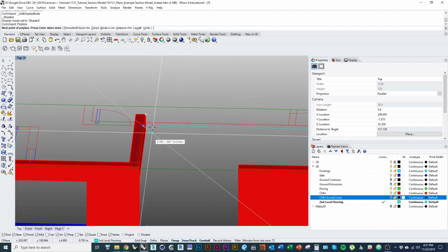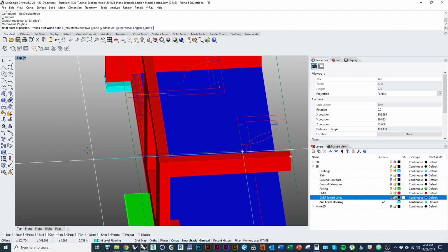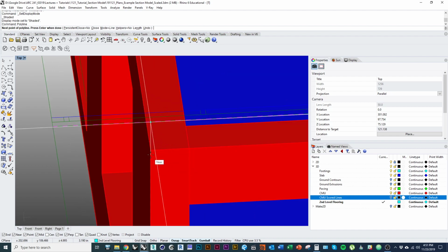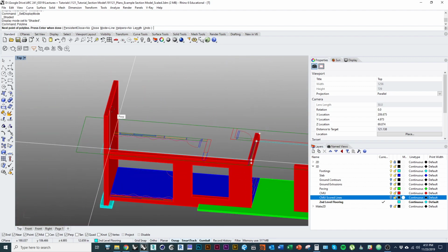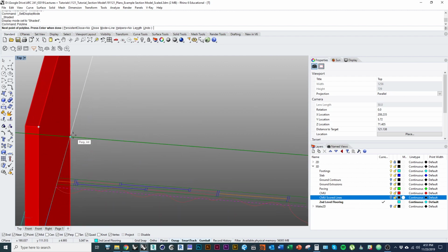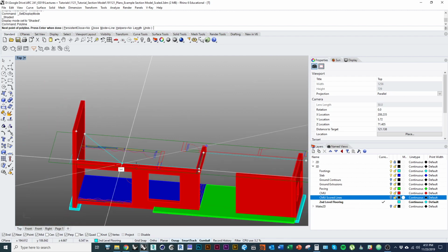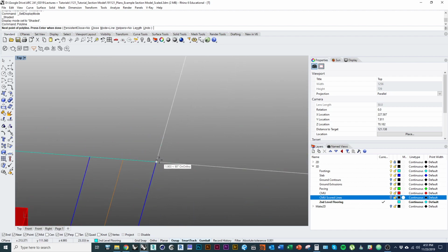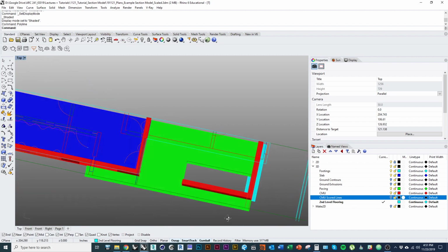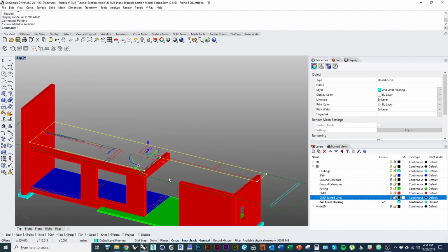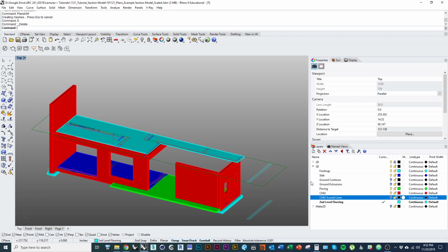And then I'm also going to use my walls below to define where certain edges should go. Oops. So I'm just holding Shift and hitting Tab to constrain my next point to that direction. And then I'm using those walls below, right here, for example, to keep it lined up with that structure below. Okay, then I'm going to make a planar surface out of that. Delete the outline. All right.